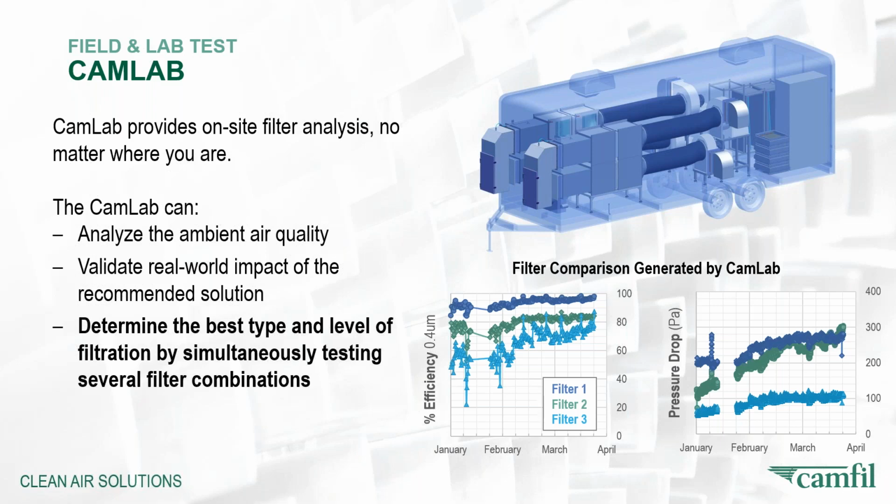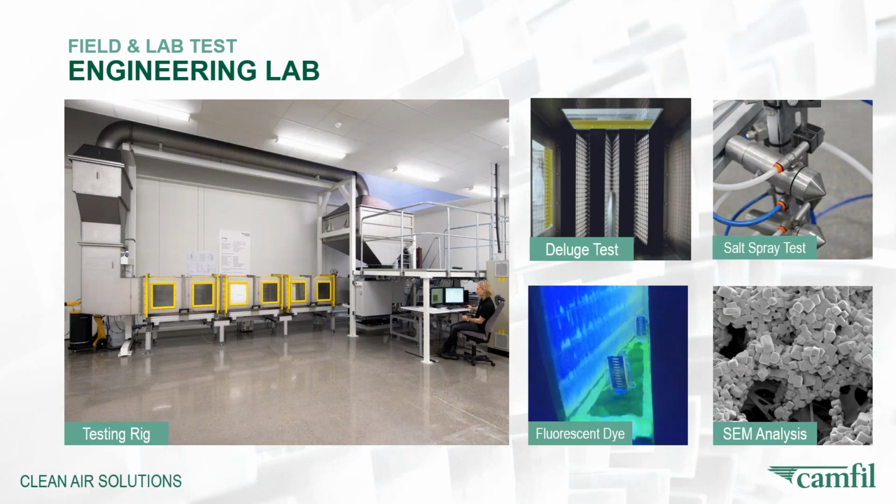It's recommended to stay at site for 3 to 6 months, so we don't just get a snapshot, we get a great overview, and we look for the worst time of the year. So the most extreme conditions in the environment, we want to test that solution. We can also perform these tests in the lab as a witness test. These labs are located in Sweden, Germany, Malaysia, Canada. They include tests such as a deluge test, efficiency test, salt, pressure drop, VDI, Aramco pulse testing, hydrophobicity, wet burst test, and electron microscope testing for the fine particulate.